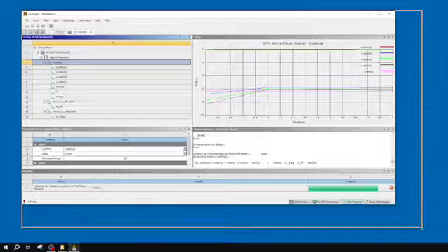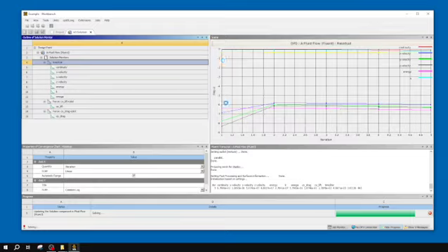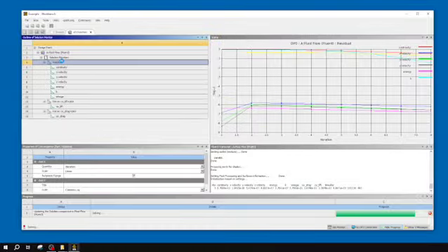I like these negative numbers. I almost never want to see a positive number in my residual plots. If I'm seeing a positive number in my residual plot, chances are something went wrong. Likely your mesh is causing an error. There might be a hole in your surface that you need to look for. Could be some bad meshing cells. That's almost always the culprit. The first time you set it up, it could also be your solution setup. So what solver you chose might have something messed up with it.